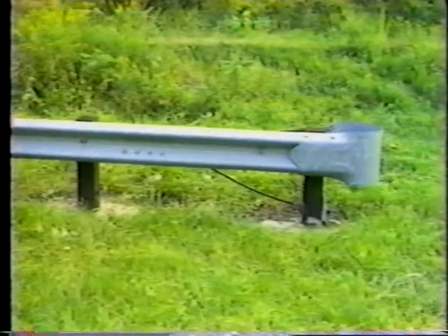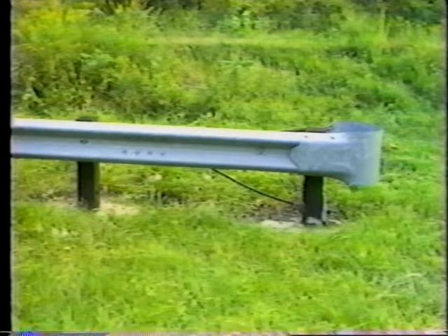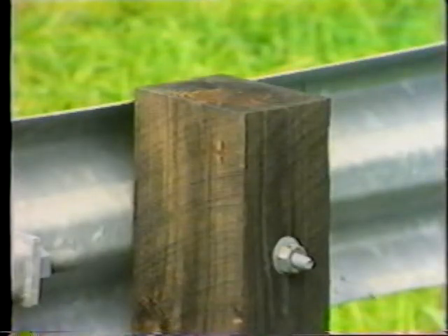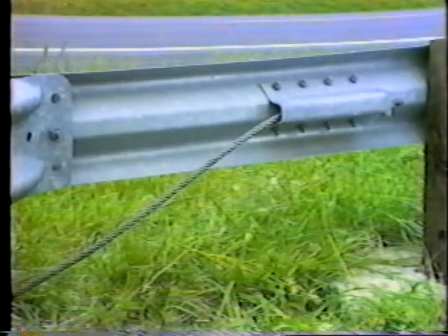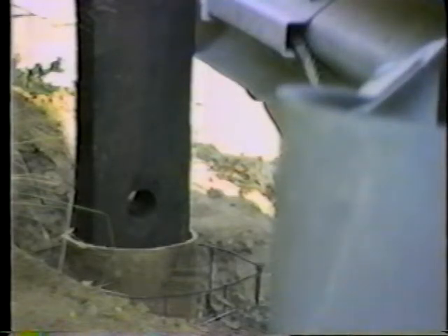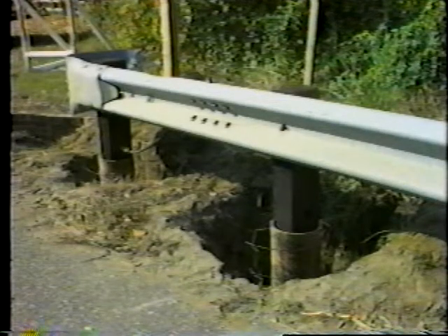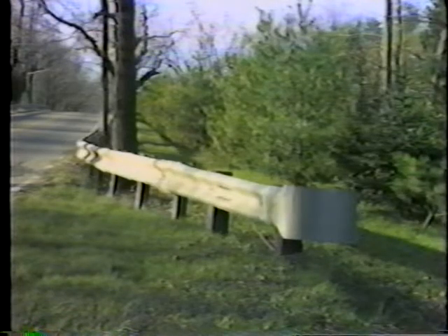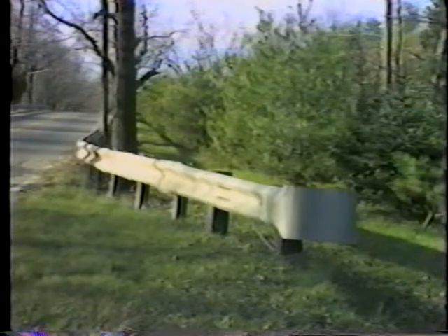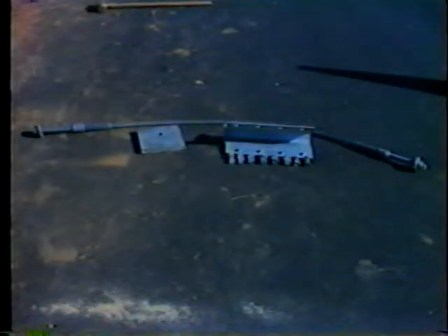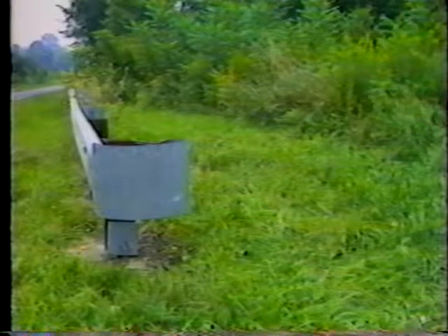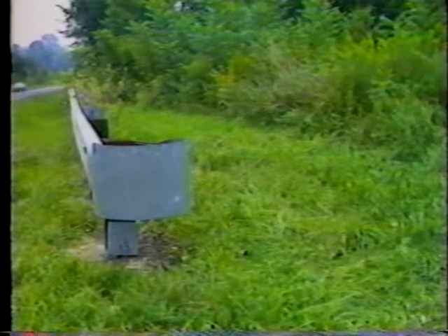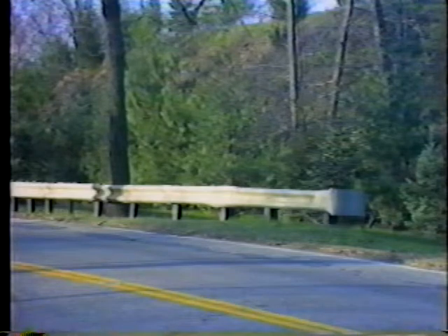There are 7 key elements that will normally determine whether or not the BCT will function as designed when impacted. These elements are post dimensions and the actual spacing of the posts, cable size, attachment, and tensioning. The breakaway system, either the hole in the wood post or the slip base on the steel post, footings of the first 2 posts of the system, the 4-foot parabolic flare in the last 37.5 feet of the rail, a critical element, the hardware used to connect the system, and available recovery space behind the end treatment itself. Post size and spacing are obviously very important.